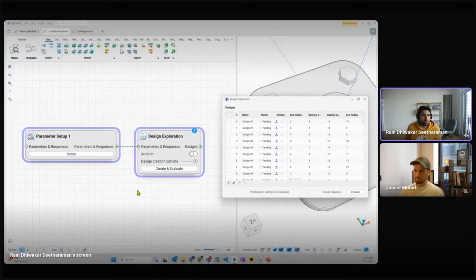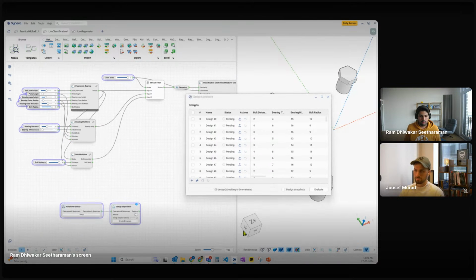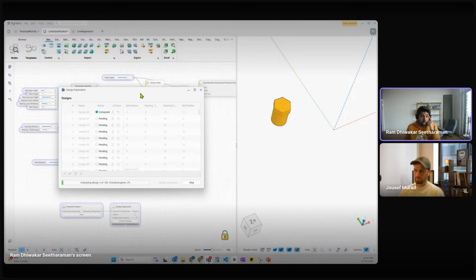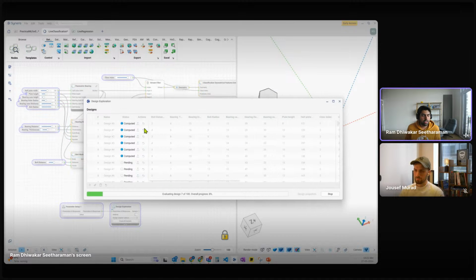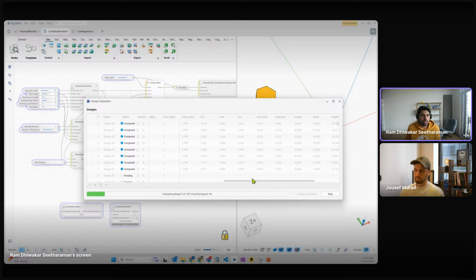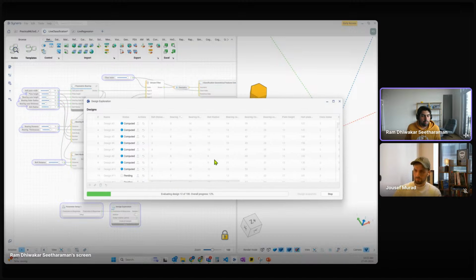and then I can already click evaluate. Let me just turn on a nice visualizer for now. And yep, let's just go. So basically, I can then start evaluating, and I can already see the parameters will start to vary. So it's already generating many geometries now. And what is happening is it's basically generated a set of parameters that it can vary, and we already see that it's starting to get the responses out. So right now, it's just sampling a lot of these parameters and working on them. So this is how I can create a data set.